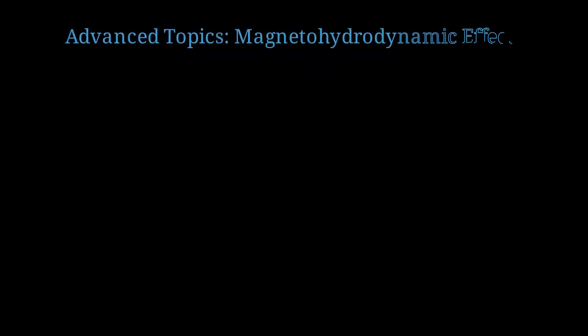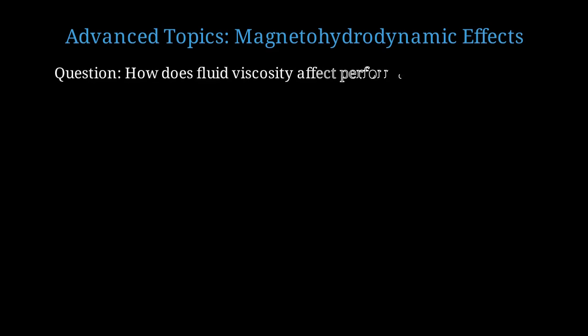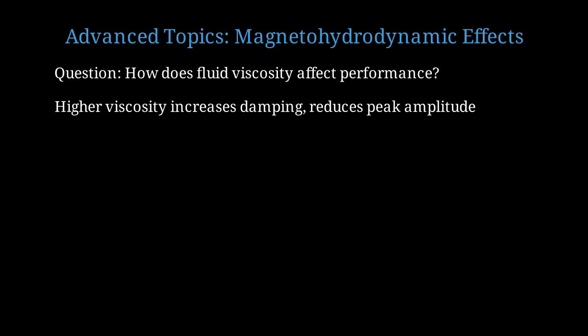Let's touch on some advanced topics, specifically magnetohydrodynamic effects in ferrofluidic systems. An important question: how does the carrier fluid's viscosity affect harvester performance? Higher viscosity increases damping, which reduces peak oscillation amplitude. This decreases power output at resonance but can broaden the effective frequency bandwidth.